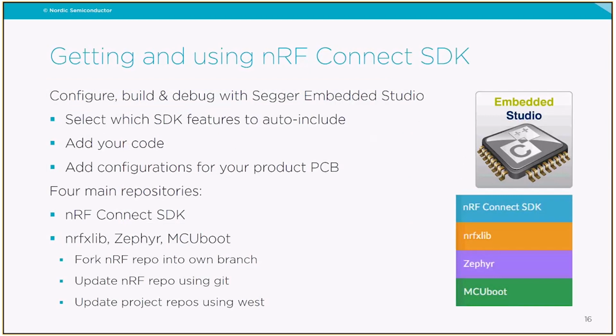Like I said, we do use Segger Embedded Studio to configure, build, and debug. You can then select which SDK features you want to auto-include, add your code, and then you can also add configurations for your product PCB. There are 4 main repositories, 4 main folders. So that is the nRF Connect SDK, you have nRF, nrfxlib, Zephyr, and MCUboot.